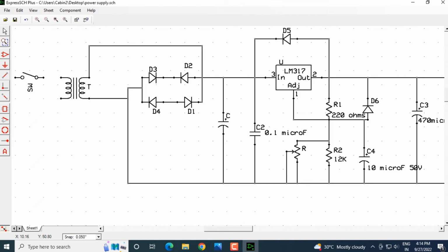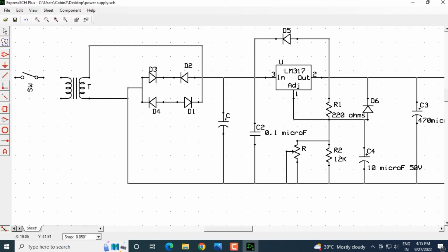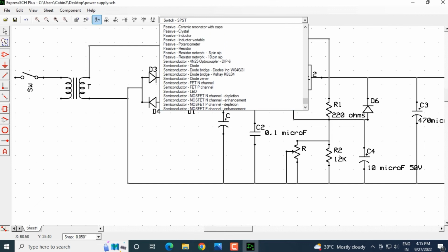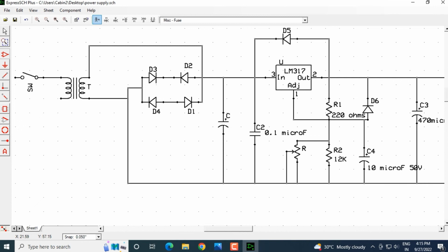And yeah, that's a switch which is connected with this particular pin. Yes, it's connected here, and we have another fuse connection here. This is the pin, and we have the fuse. So let's select fuse. Is it available? We need to check it. Yes, we have a fuse here. So placing a fuse here, rotate it.